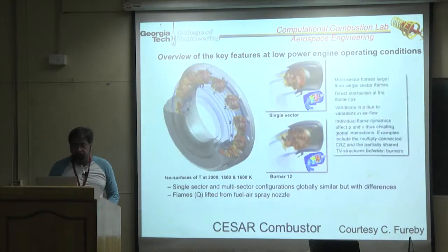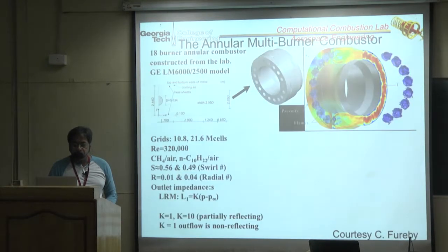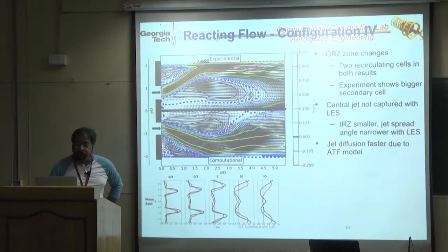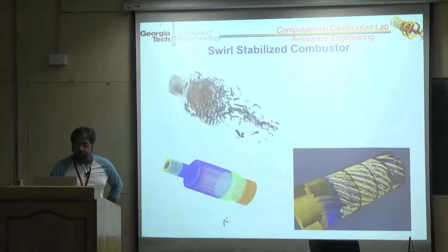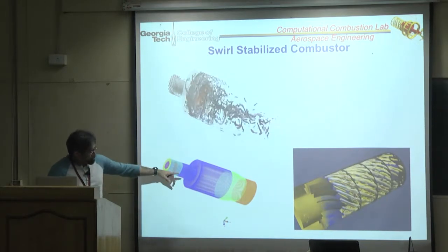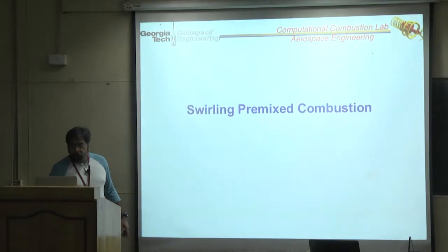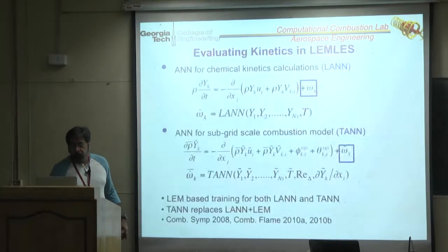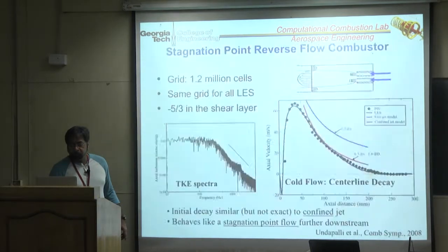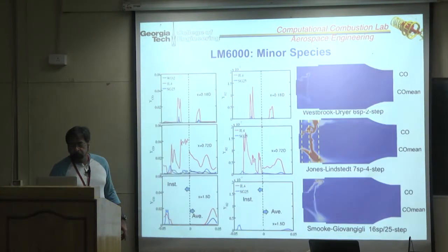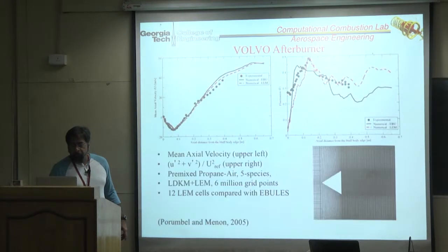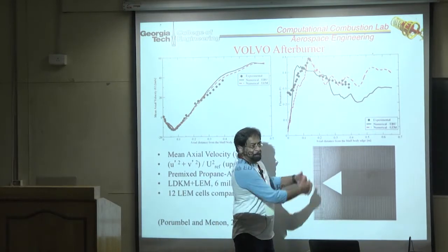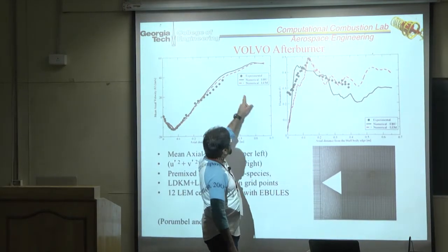And is the grid size at the Taylor scale in the whole computational domain? Yeah, so this work was done with grids like this. This is actually a different grid, but when the Volvo experiment was done, this one. There's a grid. So this grid is actually uniform, continuous. It's just clustered. But my work was using a structured grid.